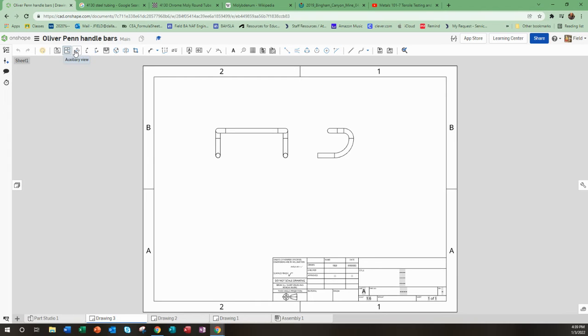But you can put in other auxiliary views. And I'm going to walk through what all of these things are up here as well when we're doing this. But I can put another projected view. So just like with how I showed you guys using projected lines, you can create projected views. And so if I create a projected view, I click on that one and drag down, I can create another. Here's a bottom view, and maybe I can even up here create a top view.